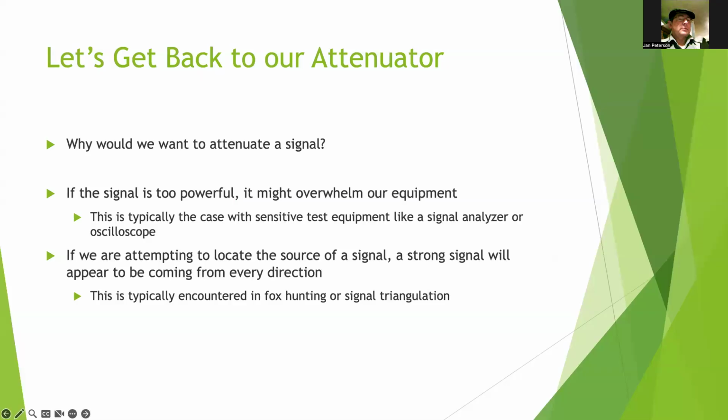Well, when you have a snazzy Baofeng radio from 5 years ago or 10 years ago, those things were really noisy. They were not great. They would put out sometimes more power on their harmonic frequencies than on the frequency you were trying to transmit on. And the FCC requires that we don't do that because they don't want us interfering with other signals out there. So you can hook this up to your tinySA and transmit on it and see, oh my gosh, this is how good my radio is, or this is how terrible my radio is. And if it's terrible, huck it in the bin.